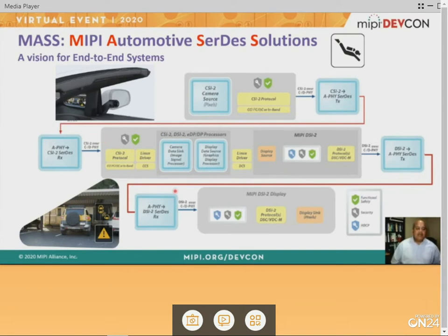The lower level illustrates how the end-to-end display receives the A-PHY data frame from the RX bridge and displays the picture using legacy C-PHY or D-PHY physical connections. Some general comments. As mentioned earlier, the end-to-end functional safety and security are maintained by a series of MAS specifications designed to work together. The CSI-2 and DSI-2 protocols are not transcoded between the device and the A-PHY bridge.